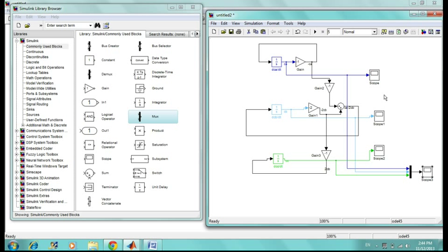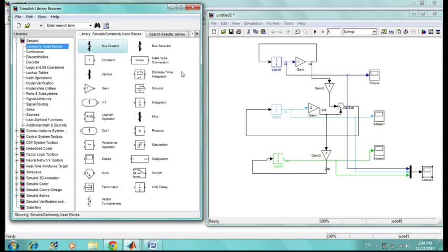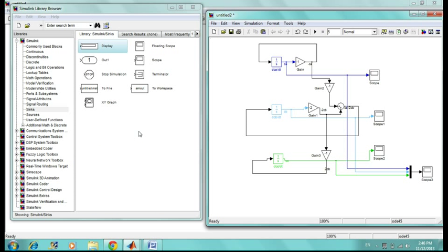In order to display your result, to see exactly the value of the concentrations of A, B, and C at this time, which is 5, you go to another block that will display the value exactly. Now to display the value exactly at this time, instead of plotting or having figures, you can use another icon as I said before, which is the display block. This block can be found in the sinks category here.